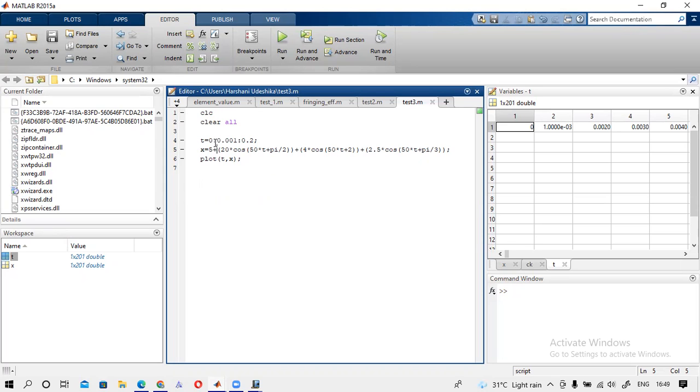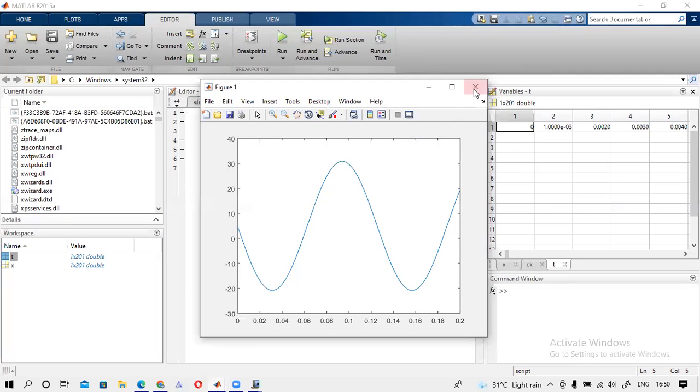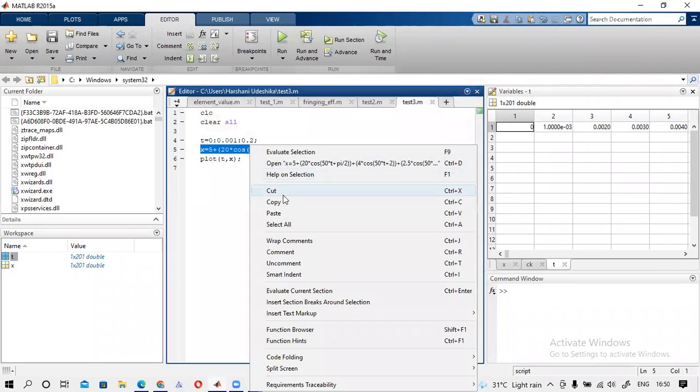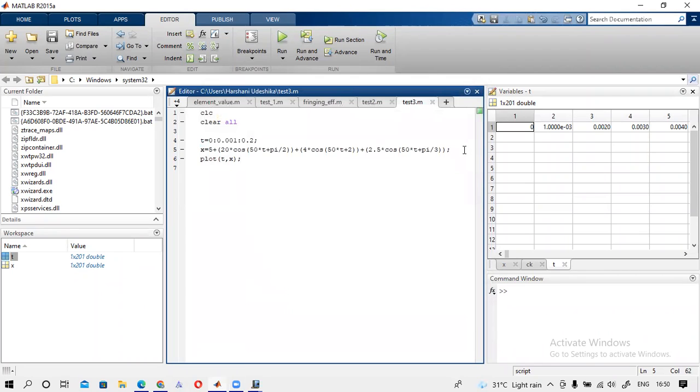So if I add any DC component, the signal will not change. But if you observe, you can see a DC shift, a DC offset. Can you remember that there is a button in the signal generator saying DC offset or something? When you set that DC offset, some DC component, minus or plus, will be added. Let me show you.